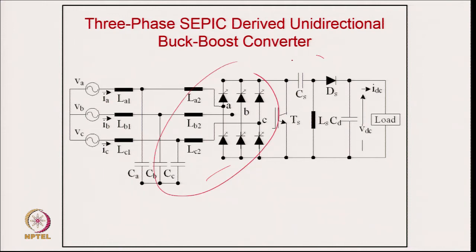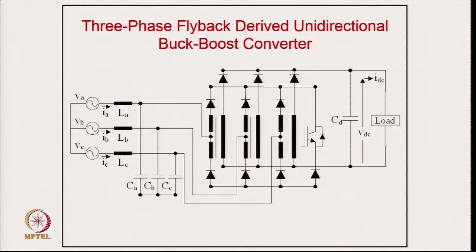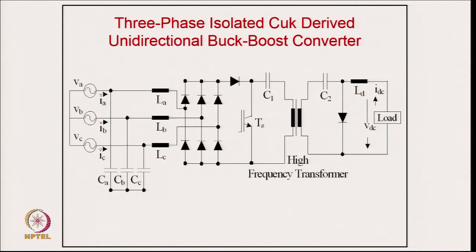Then you have the Cuk converter or SEPIC converters, which can give the buck boost operation, and this is Vienna rectifier 2, where the buck boost is derived by only one switch. It is an interesting circuit and you are able to have current wave shaping with only one switch, with the injection done properly to get the regulated output voltage of buck boost operation with the help of a single switch, similar to a flyback converter.